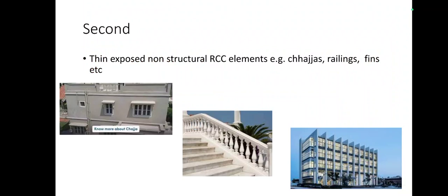We just protrude some reinforcement of 8 or 10 mm and make the slabs protrude outside. The sunshade is provided to prevent the entry of rainfall through the windows and also for protection against sunlight. Since it is a very thin element, water will enter the sunshade concrete and reach the reinforcement, as the cover depth is very less.